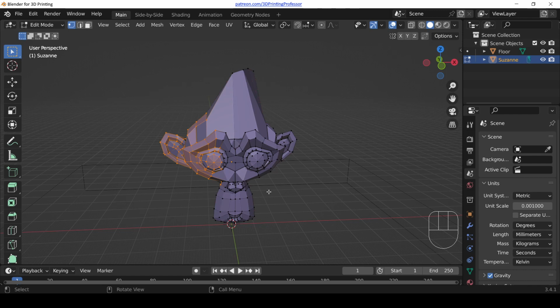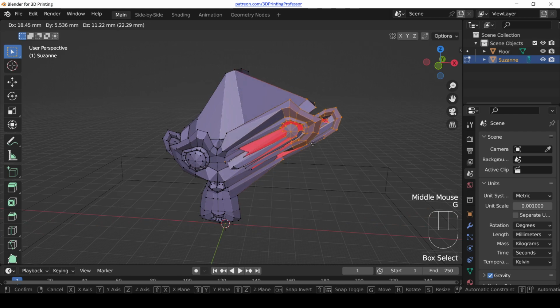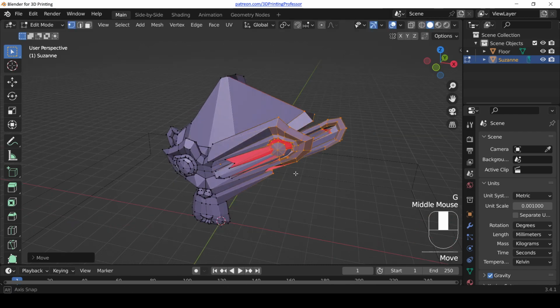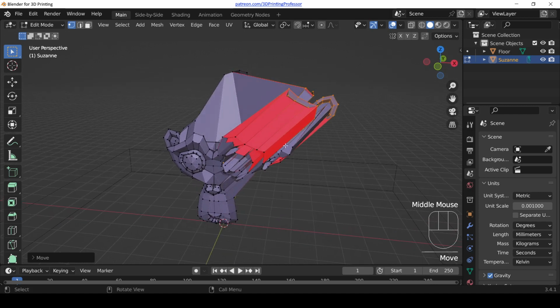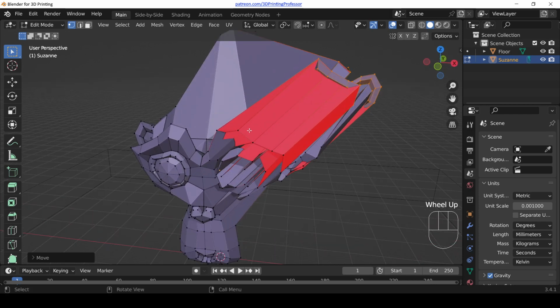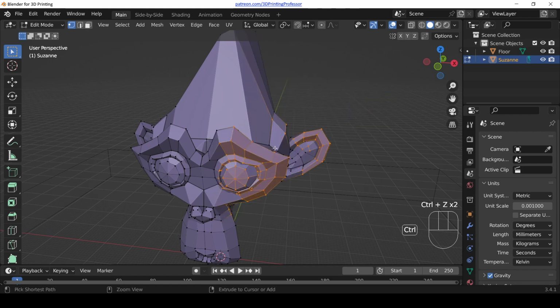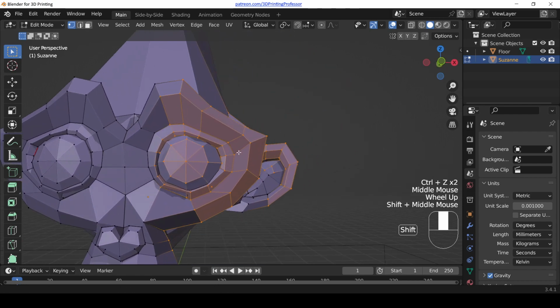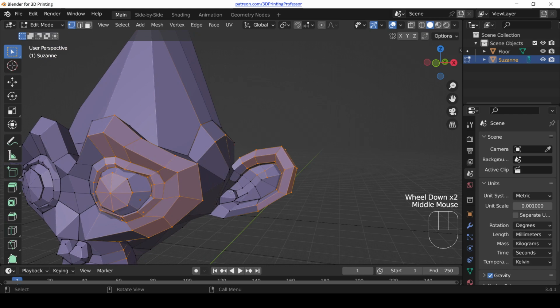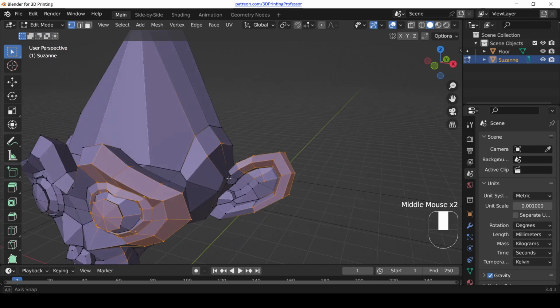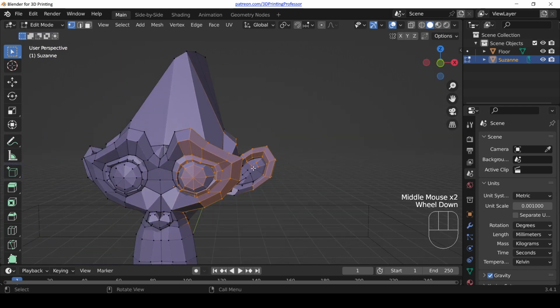But you might notice something. Select a part of Suzanne, any part, doesn't really matter, and then move it around. And you might notice that for some reason we're getting some immediate broken geometry. Why? What's happening there? What's happening is we didn't select the vertices that we couldn't see. So undo back and notice, if you look close, that there are some faces that aren't selected, and there are some vertices that weren't selected because we couldn't see them. So how do we fix that?